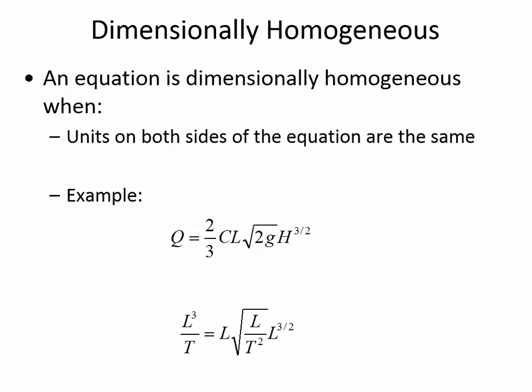The length, which is the width of that weir, has units of length, meaning meters. Inside of the square root term, you can see there's 2g, and g has units of meters per second squared. Then h is the height of the water, and you measure that in meters.